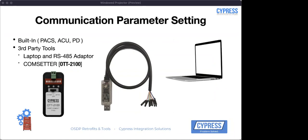Another tool that we have is the OTT 2100. We also call it the ComSet tool. The idea behind this is to configure those parameters we mentioned earlier. If you don't want to drag your laptop out of your bag, or you're in the field and you're up in a bucket or something and it's not easy to configure your device, you can pull the ComSet tool out, plug it in, set a couple of dip switches, turn it on, set the parameters, and then you unplug and you're up and running. So the trace tool is more for if you have problems, and the ComSet tool is more for the actual configuration to get you up and going in the field.